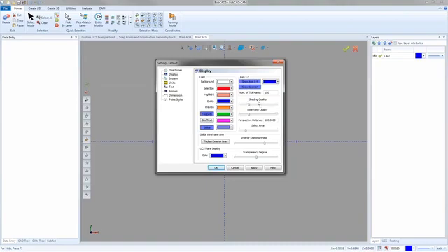The big note I have with using any of these quality options is really if you don't have a graphics card in your computer, if you're maybe running a laptop that doesn't have a graphics card, you're probably not going to mess with these too much. If you have a dedicated graphics card, we recommend at least 1 gig of RAM built into the graphics card dedicated, but most of them you're going to find now are 2 gigs and up. If you got one of those that has its own dedicated video memory, yeah, go ahead and move these up. I have a graphics card in here, and this is still where I run my system at. Maybe once in a while when I go into the settings part, I'll turn it up to about 3/4 of the way, but unless I really need to, I usually don't max it out just because it can slow down a lot on the system.